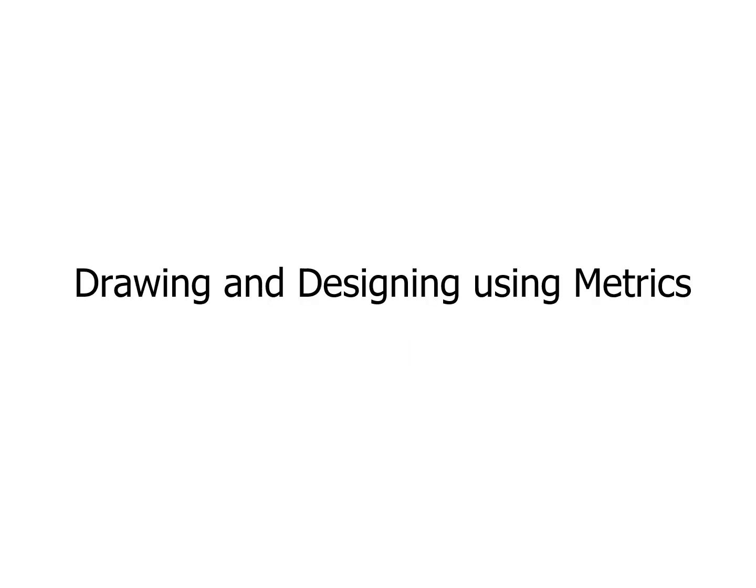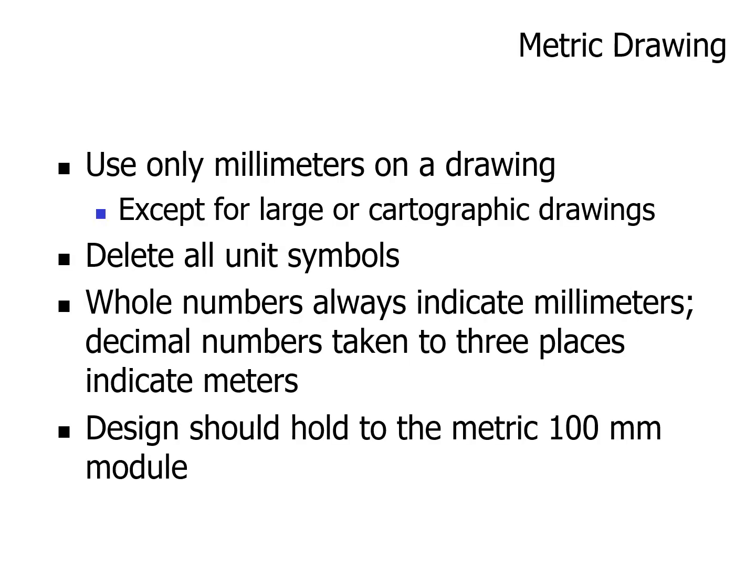Now, drawing and designing using metrics, use only millimeters on a drawing, except for larger cartographic drawings. Delete all unit symbols. Whole numbers always indicate millimeters. Decimal numbers taken to 3 places indicate meters. Design should hold to the metric 100 millimeter module.